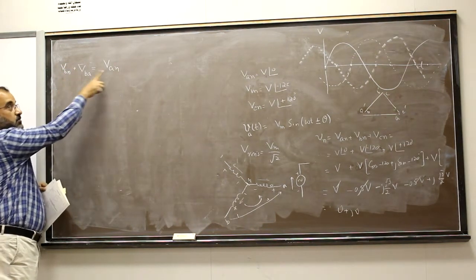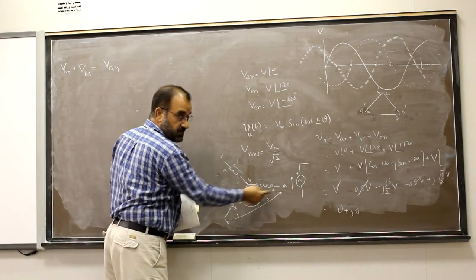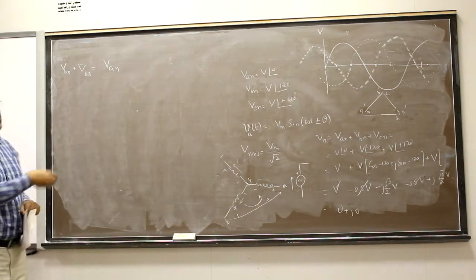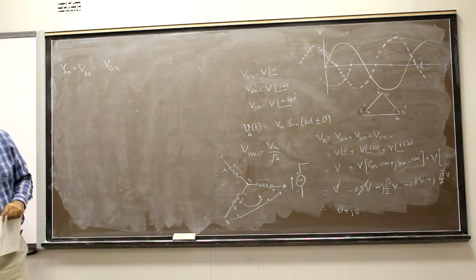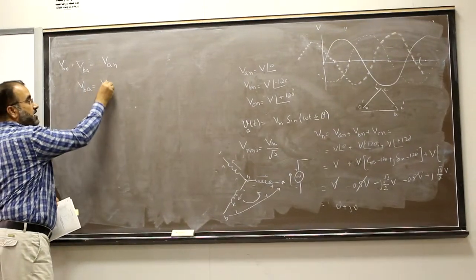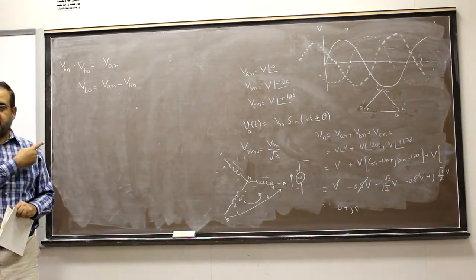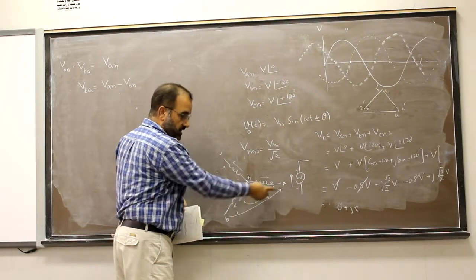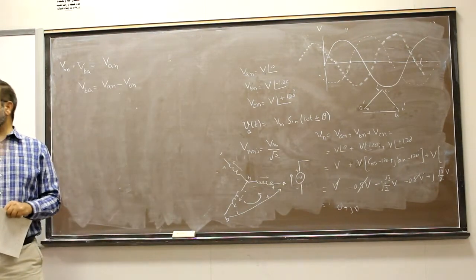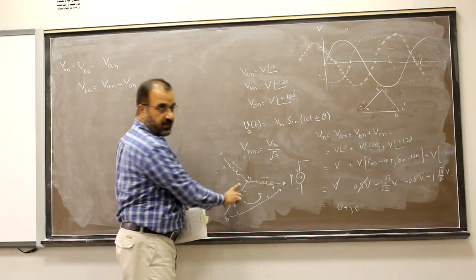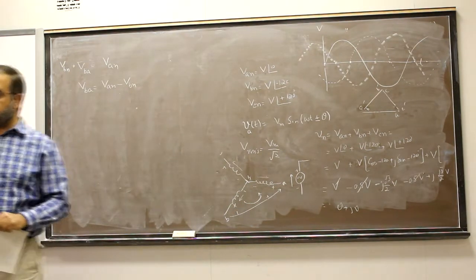Okay, rise plus rise is equal to drop. So this is rise, this is drop. When you calculate this, take the loop. Okay? So in this case, you know the VAN and VBN. What is unknown? VBA. So you will calculate VBA. It will be equal to VAN minus VBN. The equation tells you, I do not tell. Minus plus, minus plus, minus plus. And from B to A again it is minus plus. So if you apply Kirchhoff's voltage law, voltage rise is equal to drop, and this is again voltage rise. So put it on one side and the other side, and you will get the equation.